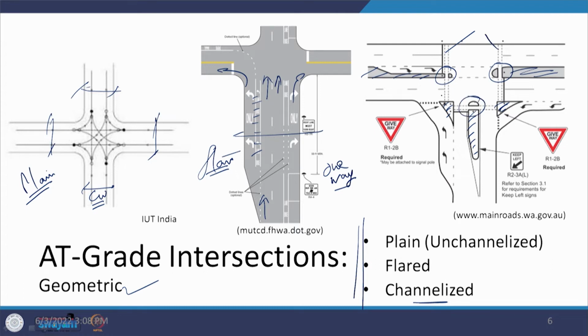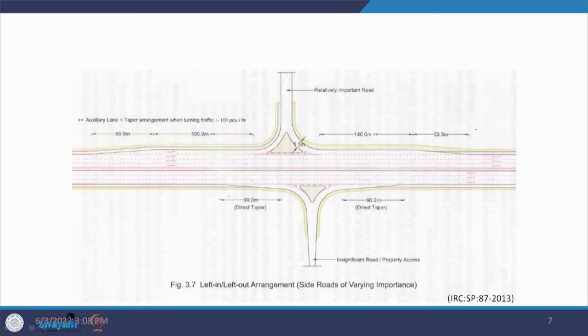There is also a gap in this median, and the pedestrians come to either of these, but from here they need to be shifted to the other side. So, there should be connectivity by way of which the pedestrians come to the curb side. At the same time, because the traffic is there, for the traffic coming from here, the give way markings and signs have been placed here. There is also a right turning lane provided here, so that the traffic gets in this form, and the traffic here is taking a left turn. Let us look at a few such cases.